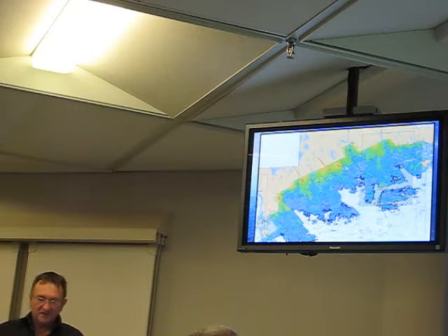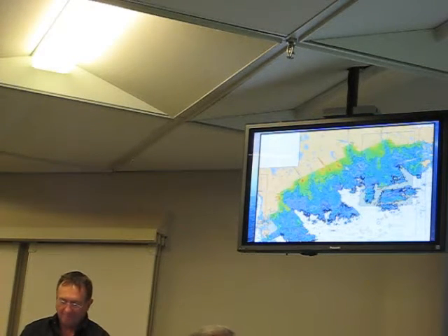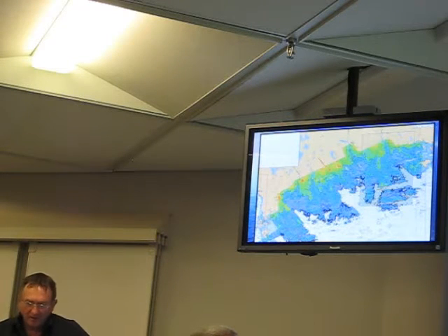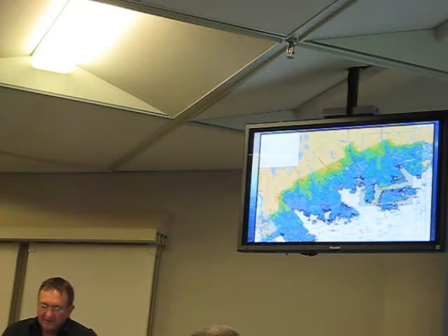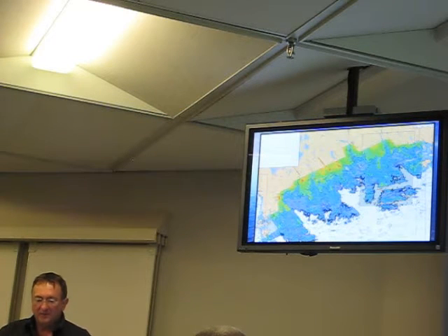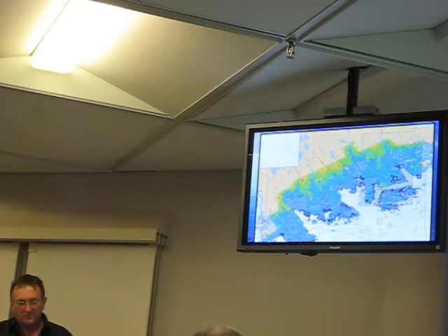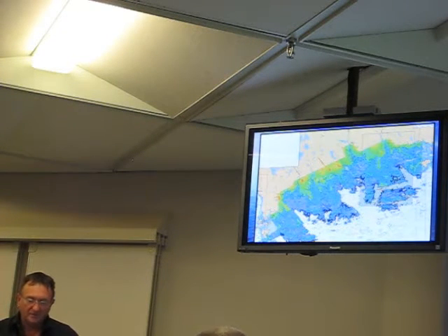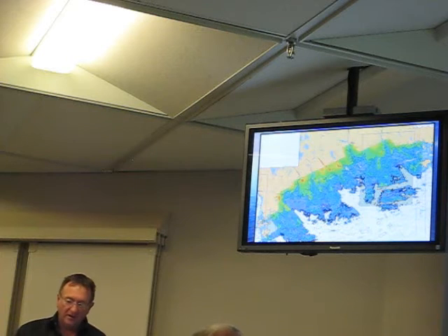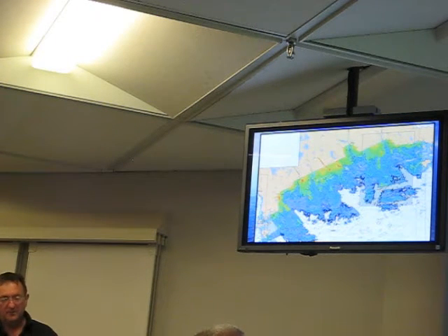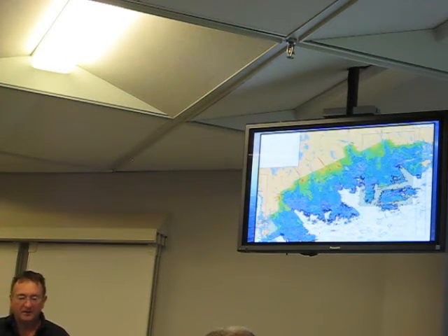So this is an example of the project from the eastern shore of Nova Scotia. Ecum Secum, we called it. Again, it's very rugged, and it hasn't been charted since the 1850s. We've been down there with boats for many years, and we keep running aground and beating them up. So we flew LiDAR and we got good results out to about 25 meters, 24 meters, probably mostly 20. So our plan is to make a new electronic chart of that area.